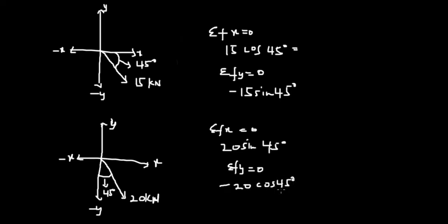So this is how simple you could approach this. Whenever you are taking the force along the x and y axis, and you meet a question where you have the angle in between a certain axis and the force, that axis becomes cos. You use cos for that axis. Just like here, we have the force along the y-axis, the angle is in between the y-axis and the force, so this will be cos.